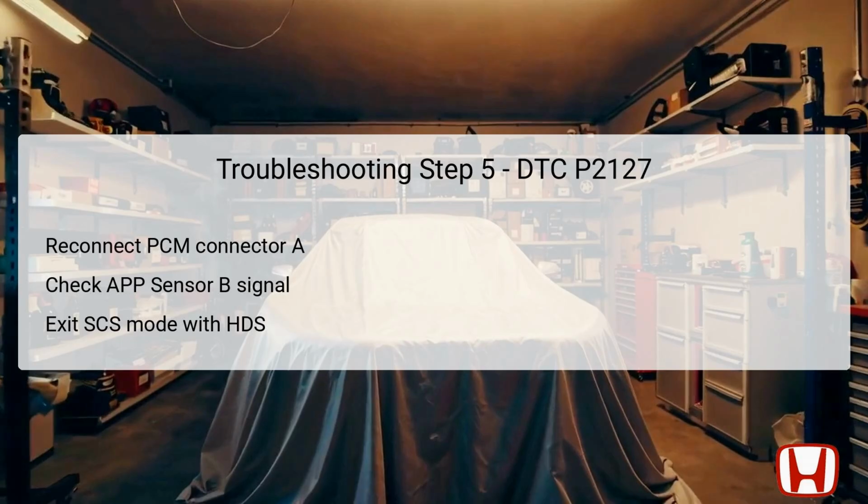With the vehicle still in the on mode, check the signal from APP sensor B. Again, the voltage should read below the threshold of 0.2 volts as required. If your reading aligns with this standard, it may be prudent to consult service information or replace the PCM if needed. However, if the threshold is not met, then replacing the APP sensor becomes necessary to resolve the DTC P2127.